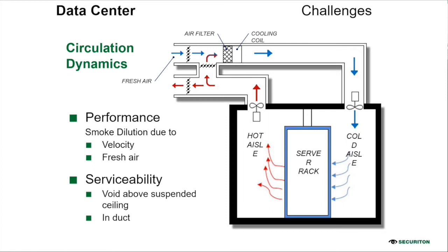Also, this arrangement generates less heat in the hot aisle, and the computer room air conditioning system in the data center works less. Air is routed back to the cold air returns, so the temperature remains low. This kind of arrangement provides a more effective air handling and cooling system in a data center.